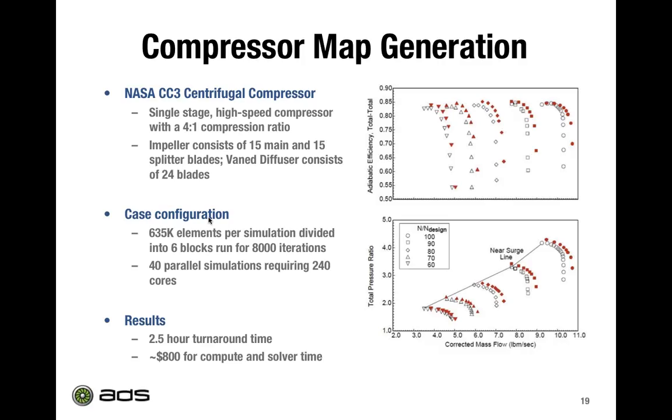So I'm going to talk now about our service, which is Cloud Leo. What we did is we took our aerospace class CFD code Leo and we put it onto these cloud servers. And code Leo is this validated density-based solver that employs the cell vertex scheme. It's highly robust and highly accurate for turbomachinery problems.